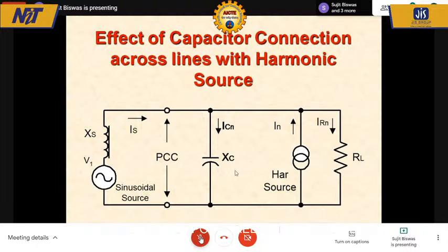So your power factor correction capacitor, which is not perfect, it has a tan delta, it has certain losses, will start becoming hot and can lead to destruction of your power factor correction capacitor in no time. The same is true of any filter capacitor that you connect, even with an LC filter. This will have an effective capacitance and will start carrying the harmonics into it, which I referred to right at the beginning as the import of harmonics due to connection of an LC series connected filter. Things become still worse as we go ahead now.